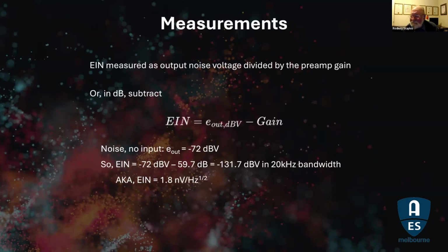Paul? Yes, it's Rodney. You mentioned dBV, which is a reference voltage of 1 volt, as I understand it, but dBu, that's 0.77 volt or 1 milliwatt in a 600 ohm circuit. Yep. I thank you for asking this. I was hoping someone would ask.